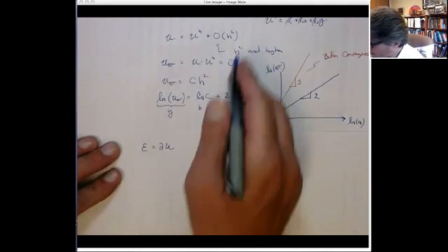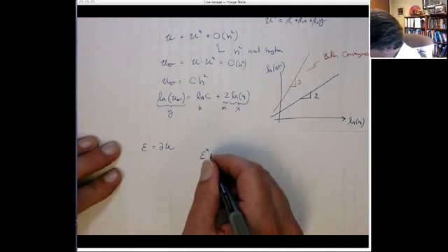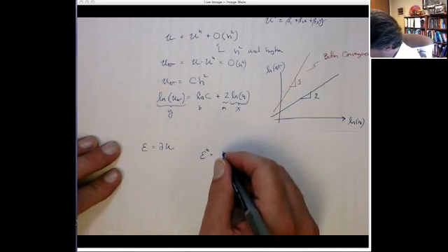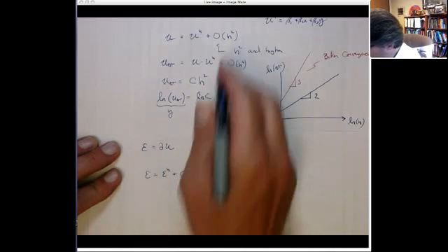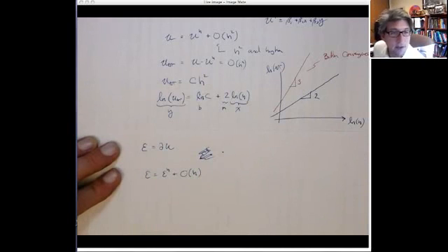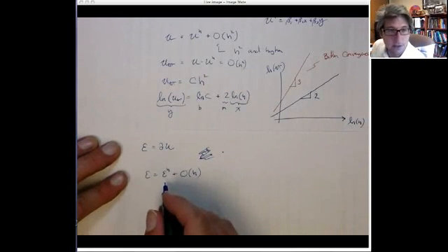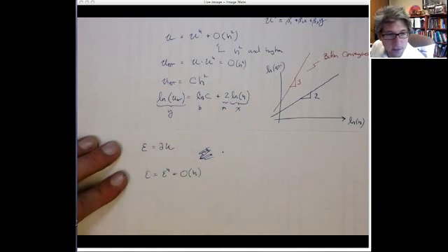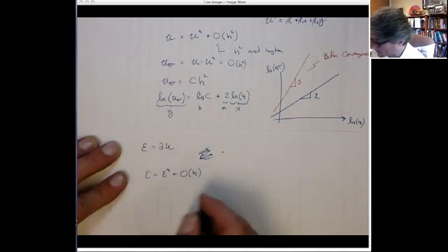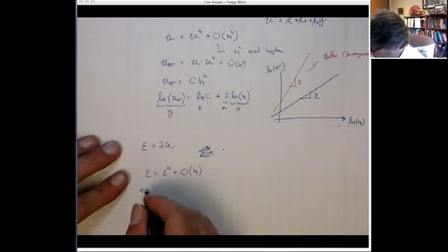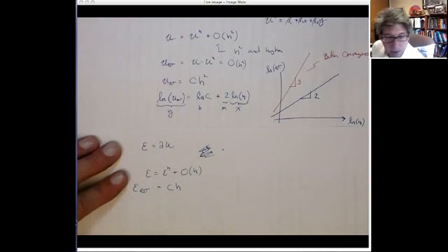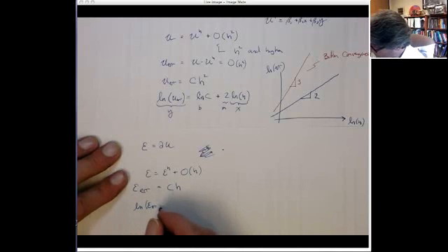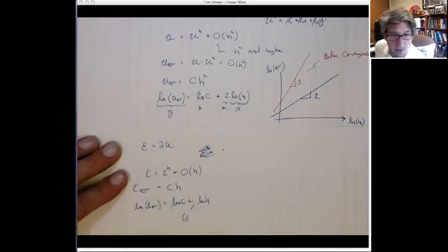So the approximation of the strain for a constant strain triangle is going to be, I'm sorry, let's do it this way. The strain is the approximation. The truncation error is going to be the derivative of this, or it's going to be order h, right? And we know these are constant terms. It's a constant strain triangle, so the strain is constant. And then the higher order term, the next one would be linear. Now in this case, you can do the same thing. The error for the strain is basically equal to some constant times h to the first. And then if we take the log of both sides, you see we get... All right, so this would have a convergence rate of 1.